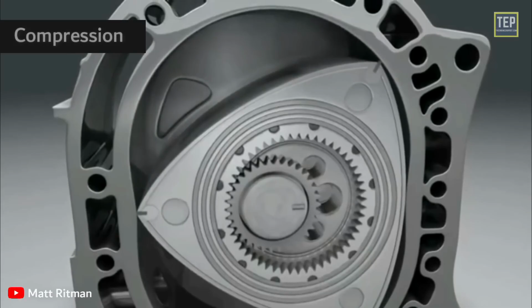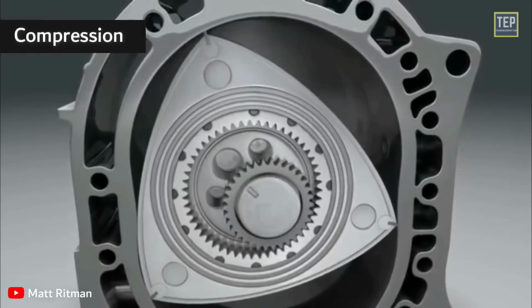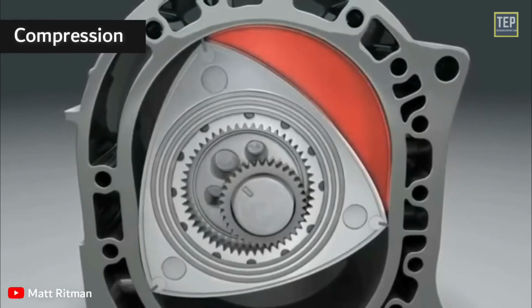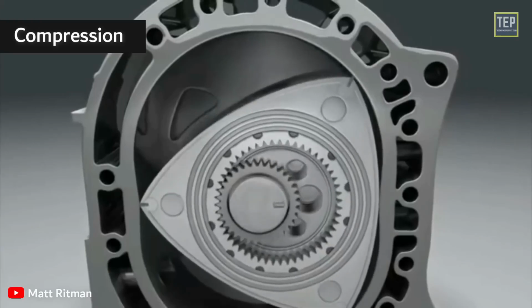In compression stroke. As the rotor continues its motion around the housing, the volume of the chamber gets smaller and the air or fuel mixture gets compressed. By the time the face of the rotor has made it around to the spark plugs, the volume of the chamber is again close to its minimum. This is when combustion starts.